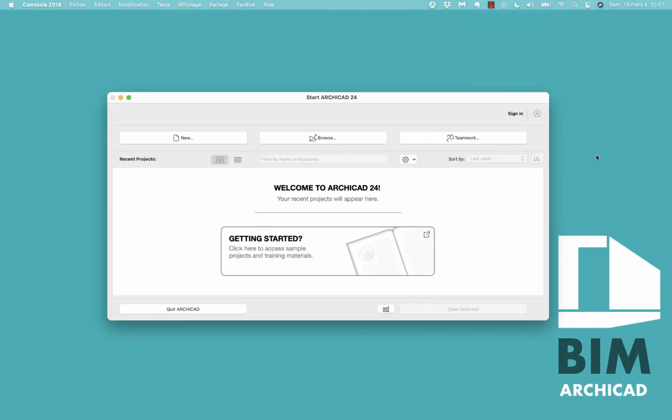When you first launch Archicad, you're going to find this window. Here you can just start with a new project, browse existing projects, and also browse teamwork files. Teamwork files are projects that are shared, that several people can work on at the same time. And right here in the space, it will list projects that you have recently opened. At this point, I haven't recently opened anything, so it's empty. So let's start with a new project.